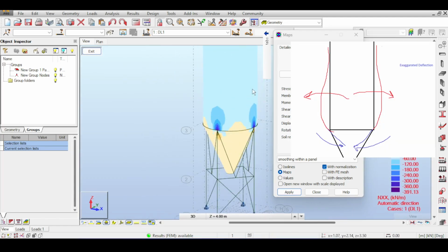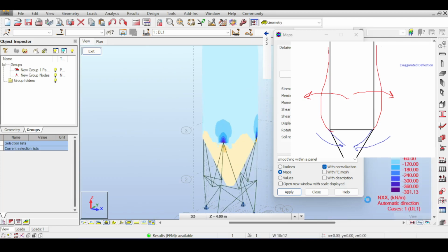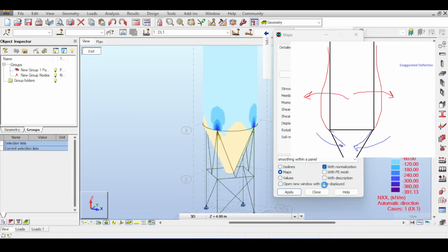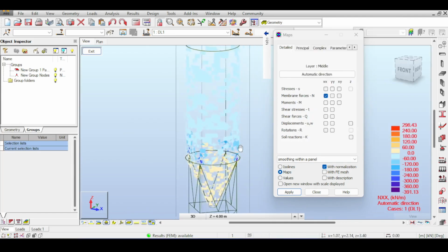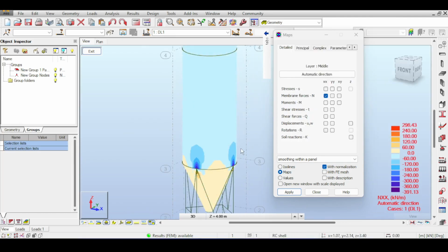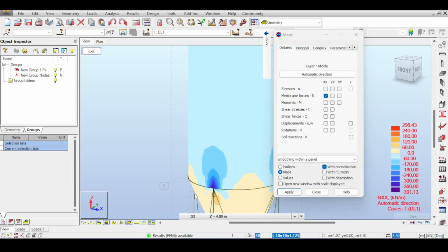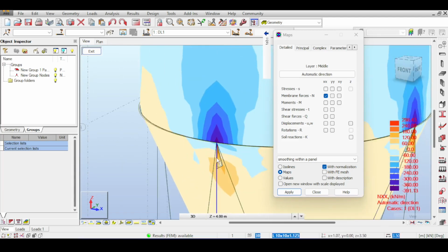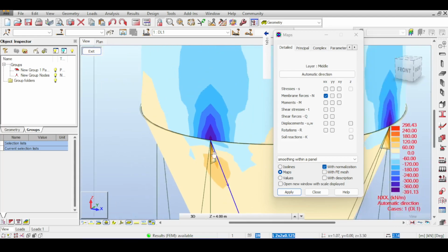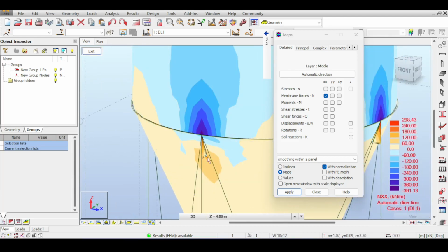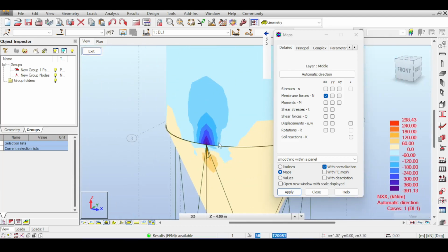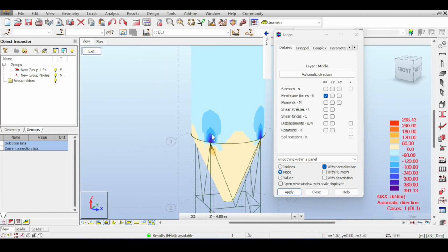You see, when this bulges out, bulging out compresses the hopper, and that's the reason why you have a hopper under compression. It's kind of like, if you have a long cantilever, then the beam inside the cantilever will bulge up instead of down. Once again, this is the hotspot of your design. It's basically where you have the connection here, and having this plate was able to divide the stress into two pieces, but still you have a stress concentration here. This is the danger zone.